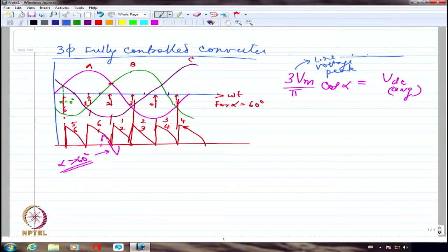So if I say 415 volts, 50 hertz, obviously 415 volts refers to the RMS value of the line to line voltage. So this question should not come up anymore. Please note it down clearly, underline it in your brain. Any three-phase equipment, the specifications are always like this.